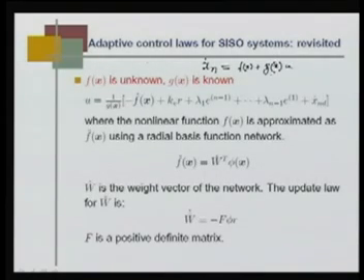But we are saying direct adaptive control because we will not be estimating f x using the system identification principle, but we will be identifying f hat x using the principle of tracking error convergence directly. Hence, this control technique is known as direct adaptive control.